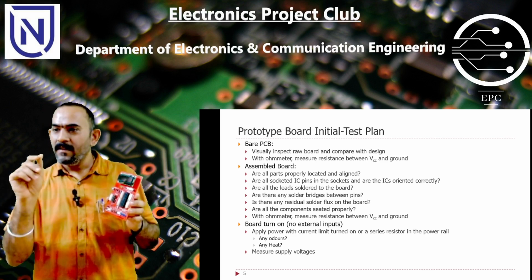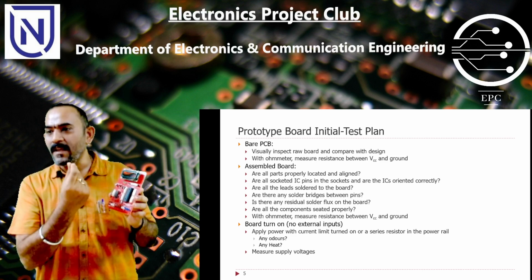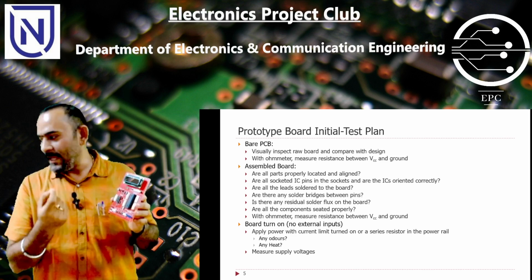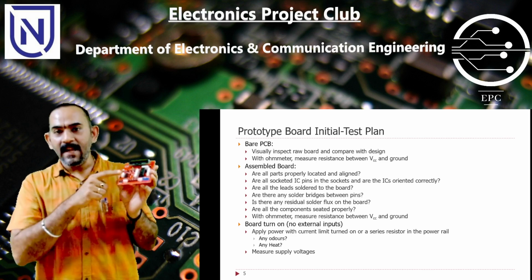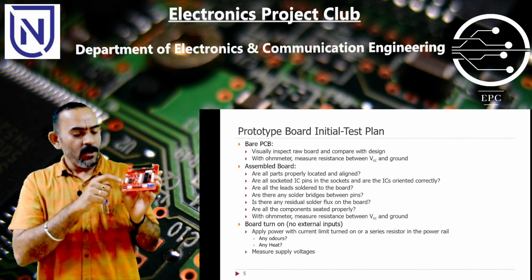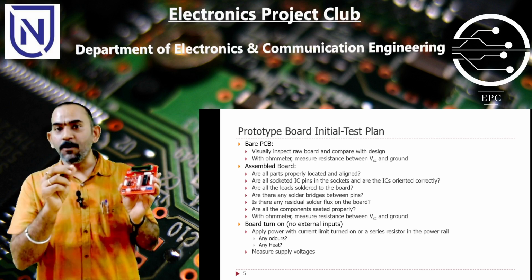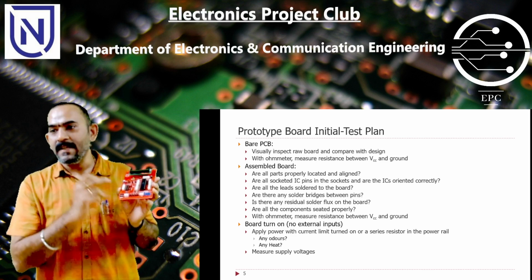First, if it is an external wire, the insulation will start melting, so you can smell it. Inside the board, because it is FR4 material, the track is inside, the track still heats up, so the top layer starts getting corroded, charred.